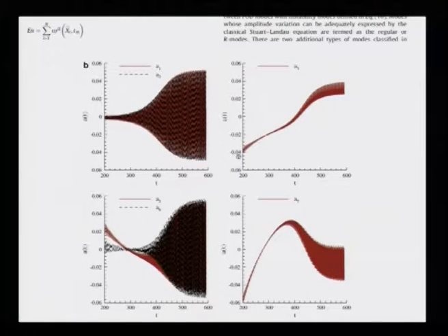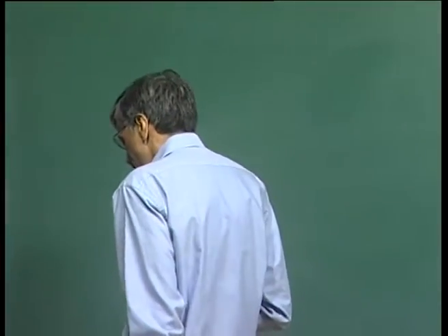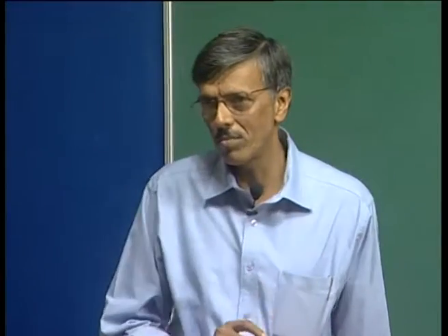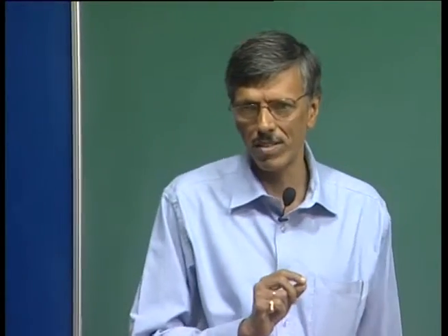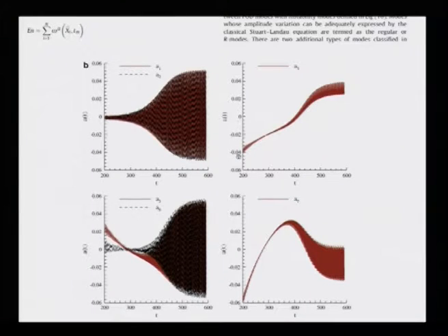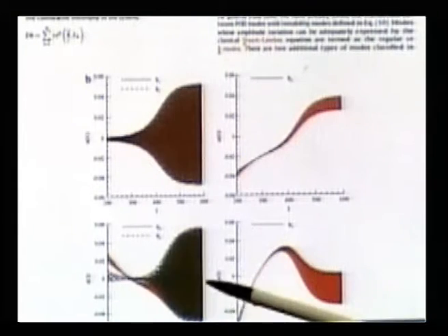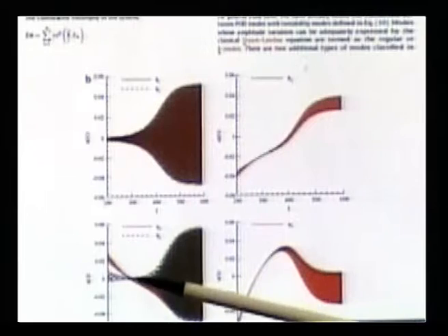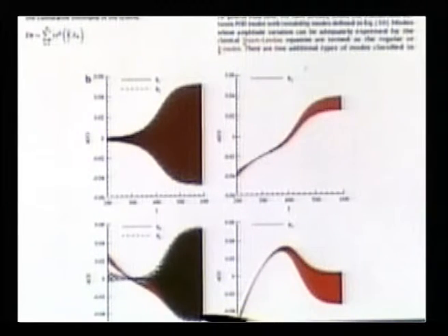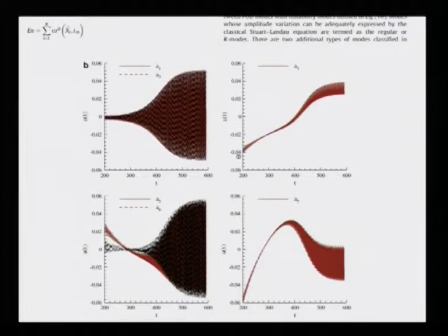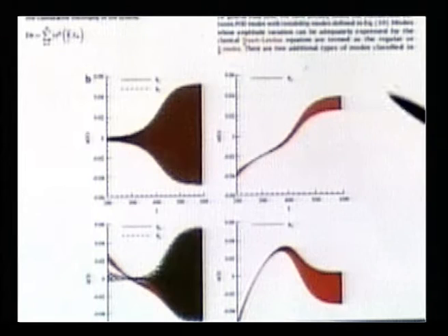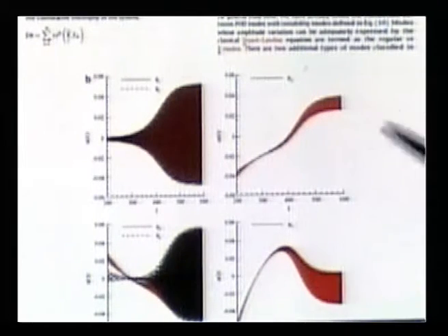So, it is very instructive for one to understand what is going on here. Our aim is to take a very stochastic system and project it on a deterministic basis, and if we do that, then what would happen? If we are getting a perfectly deterministic basis, those have to be orthogonal. 1 and 2 seem to show that, but if you look at 5 and 6, to begin with they are not orthogonally related, right. Despite that, as instability takes over and nonlinearity saturates, you do actually end up getting an orthogonal basis, right. In contrast, we have this shift mode, the anomalous mode of the first kind, the third and the 7th. That is what we are seeing here.